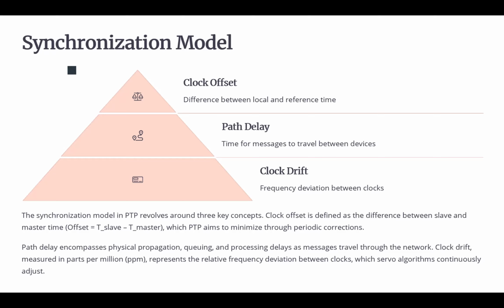As we mentioned, the errors are not just static offset errors. We have some time-dependent errors, which we call clock drift. Clock drift is a gradual difference caused by the difference in ticking speed between two clocks, because of imperfections in the hardware.